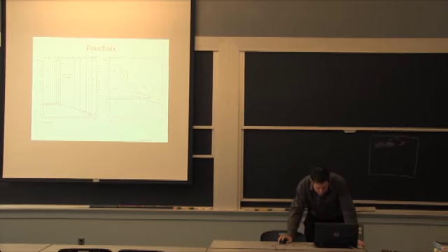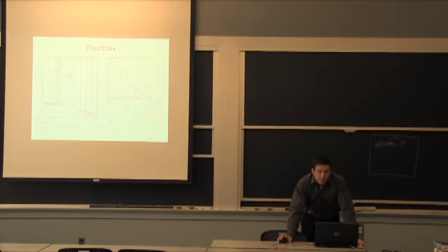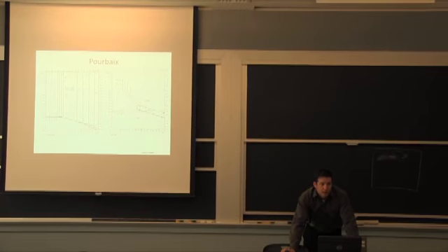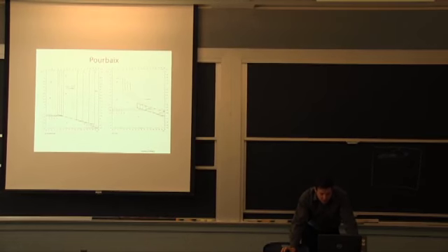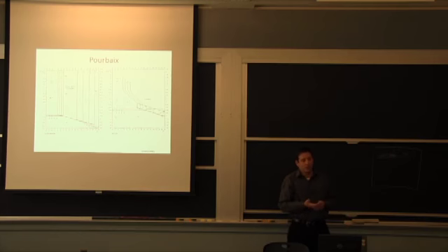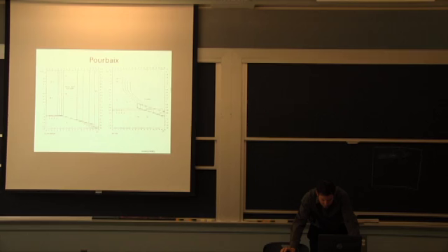If you reduce the electrical potential of the steel, you can fall into that lower zone here where it's stable. That's used with sacrificial anodes and it's also used with impressed currents. It's essentially changing the potential on the metal enough that the pH doesn't matter anymore. It's just very stable.